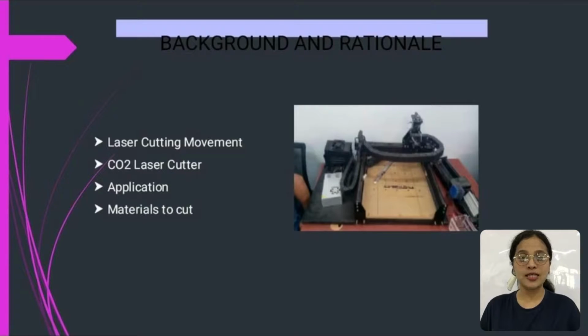Laser cutting is a technology that is commonly used in industrial manufacturing. It enables us to cut complex shapes without tools and at a speed similar to or faster than other cutting methods. The machine has 3-axis dimension. The X and Y axis is for the horizontal and vertical movement of the laser head, while the Z axis is supposed to match the height of the workpiece surface to the focal length of the laser to ensure that the material will not be damaged.